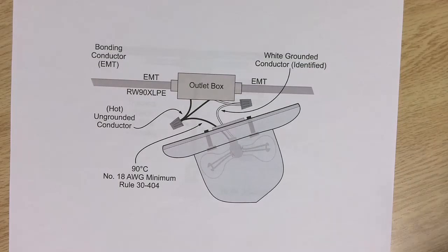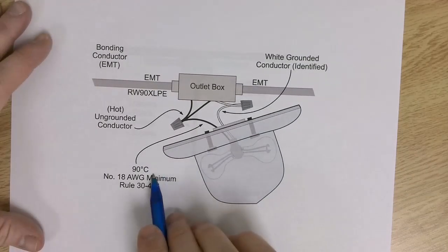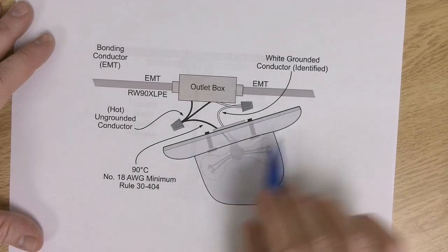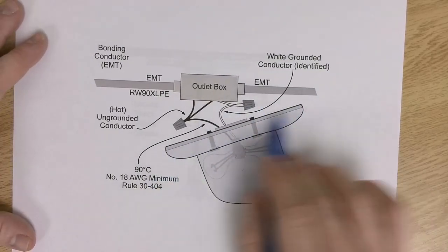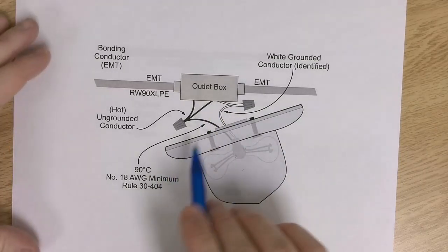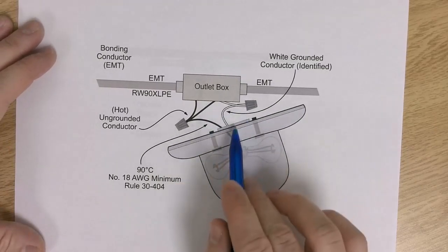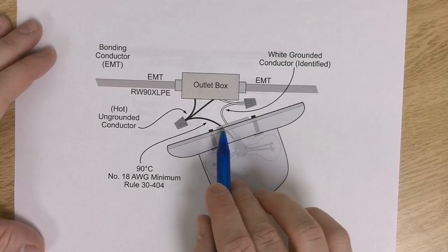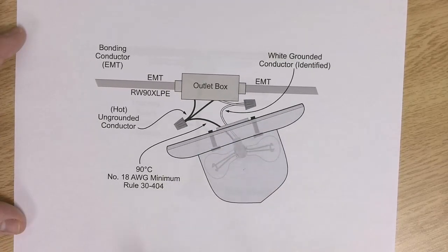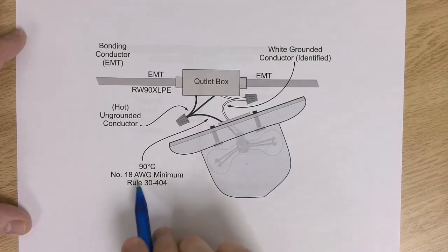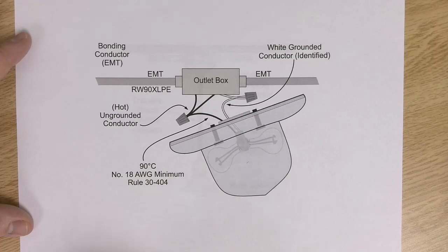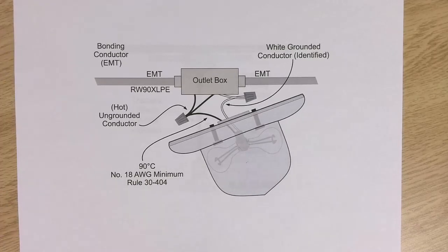But what's going on here? Sometimes you'll have a light like this. This is kind of a common setup. It has this big sort of plate to cover the junction box on the ceiling. And you'll have these little wires that are not 14 gauge coming down from your light fixture, from the luminaire. Now, why are those allowed to be 18 gauge? Does nobody check that? No inspector has ever looked at the wiring of a luminaire? No, of course not.